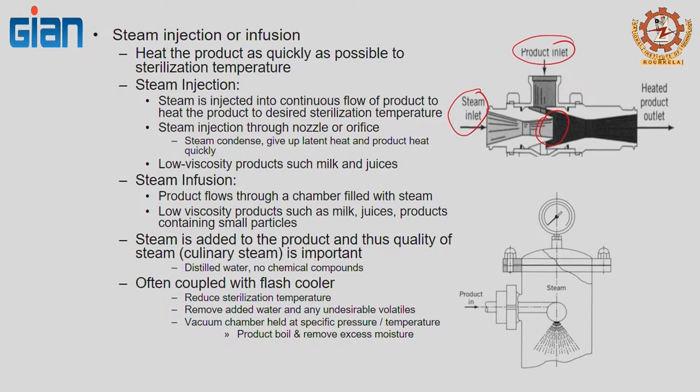Steam infusion is another version. Here you have product coming in, and then it is sprayed into a chamber that has steam, and thereby you are able to heat it. So, it is kind of those two. These steam infusion, as well as injection, systems are usually associated with a flash cooler, so that any additional water you added during the treatment could potentially be removed.